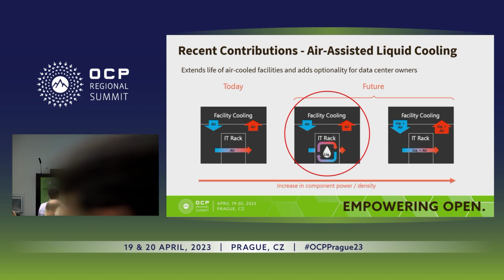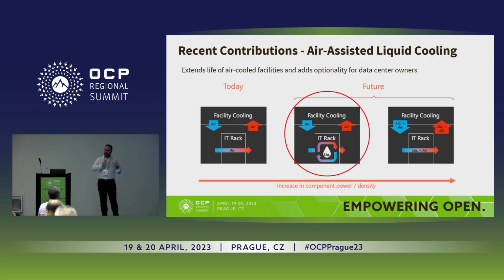But it's important to think that when the rack power density increases, the liquid is coming nearer to the microchip. And at this point, it's very important to think about liquid cooling, direct-to-chip cooling. Rear doors bring some advantages.